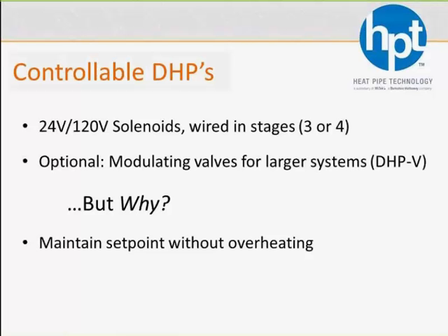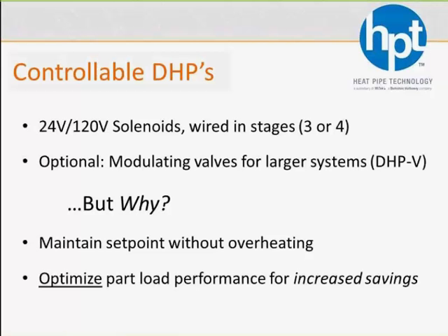And that in its own right, having that controllability is a great benefit for having these control valves. But what I want to focus on is really utilizing these valves to optimize the savings on the heat pipe by not focusing on a full load day and that design day, but focus on part load, because that's where you're going to spend most of your time. And what it does is it allows you to somewhat oversize the heat pipe, get the reheat you want during part load where you're spending more time, but then trim that reheat and cut off those circuits at those fewer design days so you're not overheating the place.